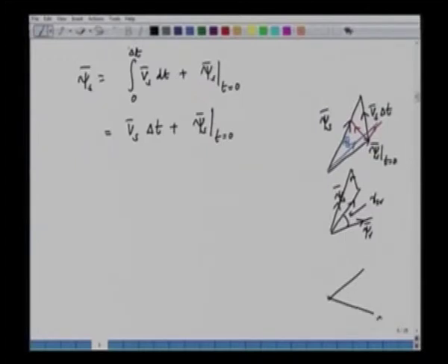This is the rotor flux psi R, this is the stator flux psi S, and if you want to reduce this angle gamma SR, instead of moving away, we can move towards the rotor flux vector. This is the resultant of the two, and hence the angle is reduced.